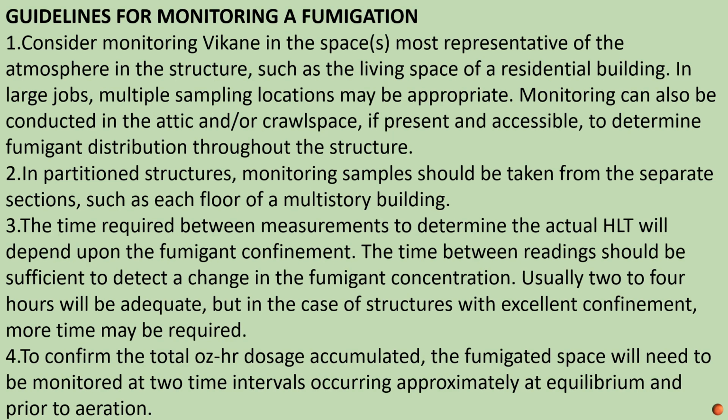Guidelines for monitoring a fumigation. 1. Consider monitoring Vikane in the space most representative of the atmosphere in the structure, such as the living space of a residential building. In large jobs, multiple sampling locations may be appropriate. Monitoring can also be conducted in the attic and/or crawl space, if present and accessible, to determine fumigant distribution throughout the structure.